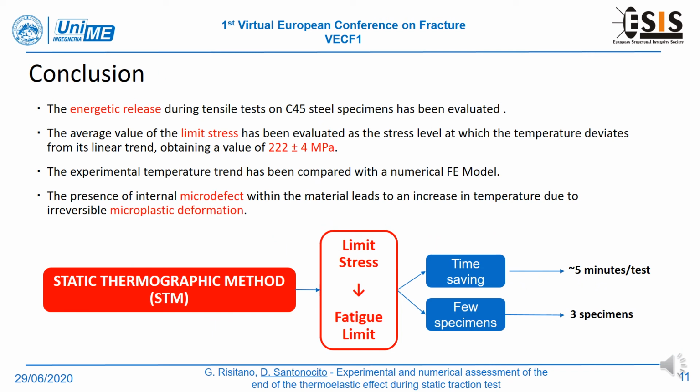In this work, the energetic release during a tensile test on a C45 steel has been evaluated. The infrared camera allowed the application of the static thermographic method, monitoring the specimen surface temperature under adiabatic conditions. It has been possible to assess the limit stress of the material as the macroscopic stress at which a deviation from the linearity of the thermoelastic effect is noticed.